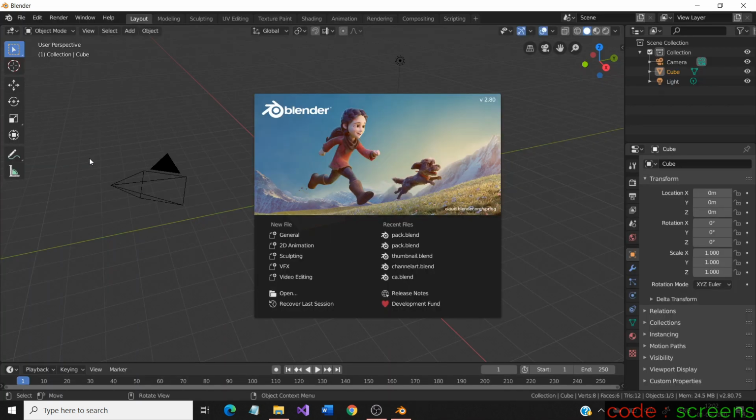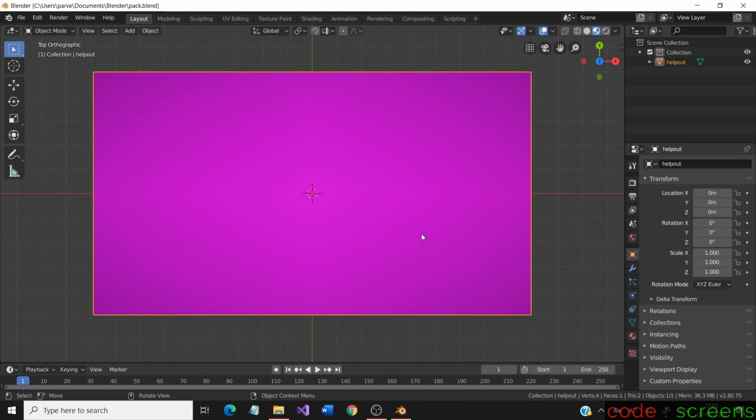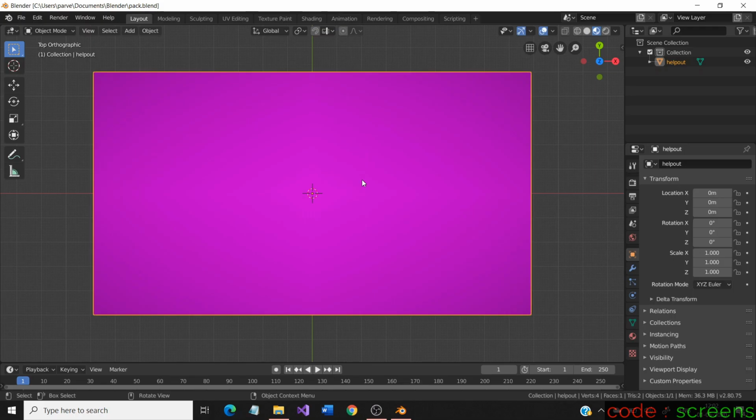After opening Blender, select the pack.blend file we saved already. Notice this. The image we loaded has disappeared. Let us fix this now. If the file created is native to the system and the image is missing, it should have been deleted or changed its location. We know that the location has been changed.